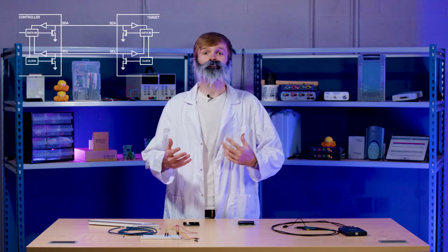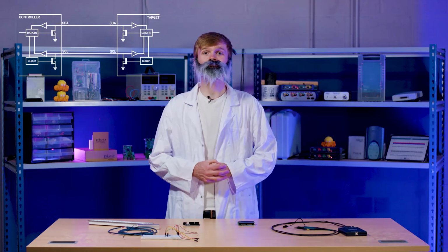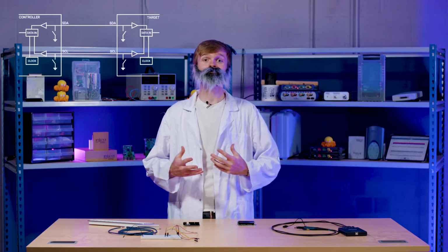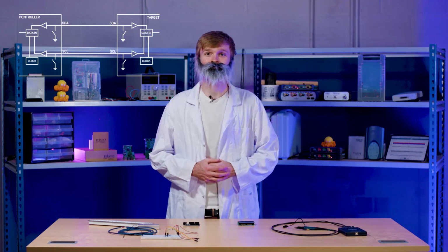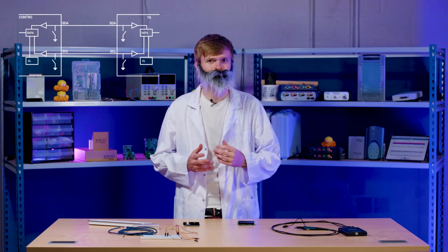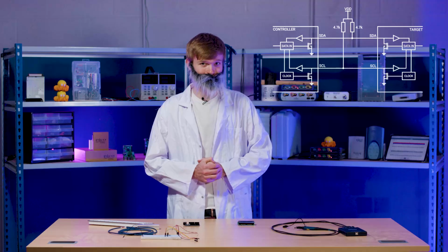To control this voltage, I2C uses an open drain configuration, meaning each end has a transistor to pull the line to ground to make it a low signal. This raises the problem: if both transistors aren't active, it will leave the signal floating. To fix this, I2C needs a pull-up resistor around 4.7K to make the signal high. The resultant circuit will end up looking something like this. This results in a signal staying high when not transmitting.